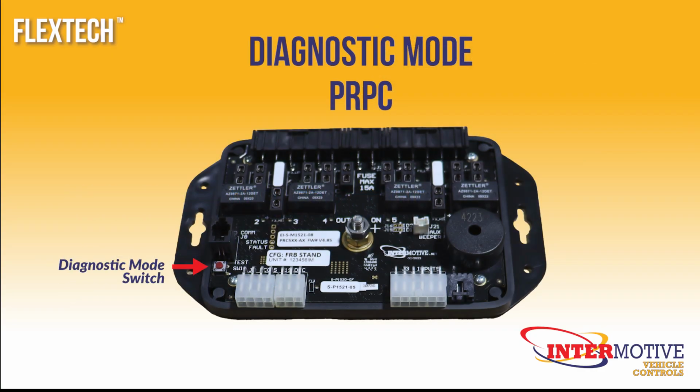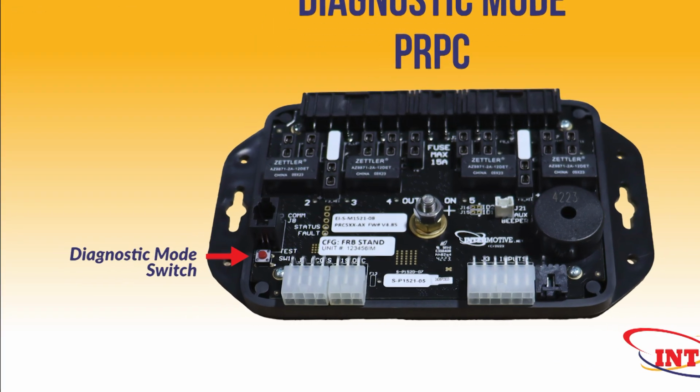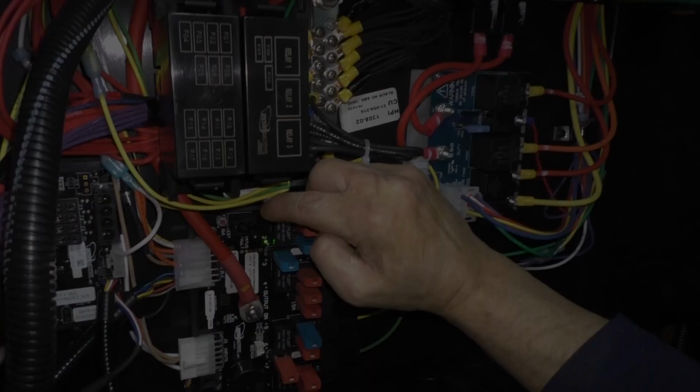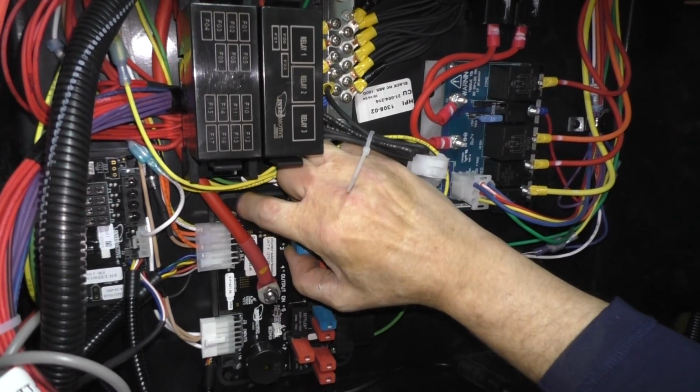Diagnostic mode. The PRPC is the FlexTech Diagnostic Hub. All LED diagnostics and fault codes you'll find on this module. On the left-hand side of the board, press the red Test button to enter diagnostic mode. If you hold the button, the fuse LEDs will light up.